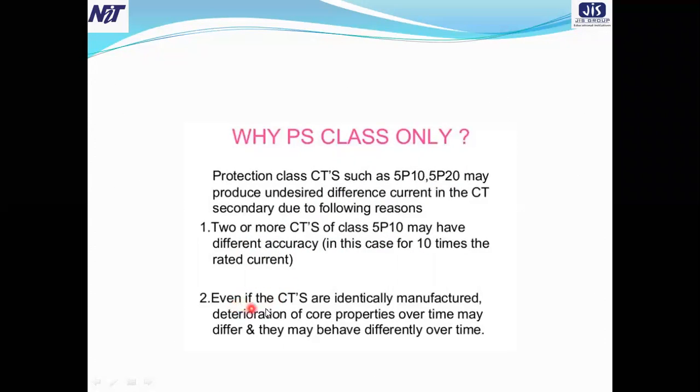Second, even if the CTs are identically manufactured, deterioration of core properties over time may differ, and they may behave differently over time. So these are the two reasons why PS class only. First, CTs of class 5P10 may have different accuracy. In case of this, 10 times the rated current.